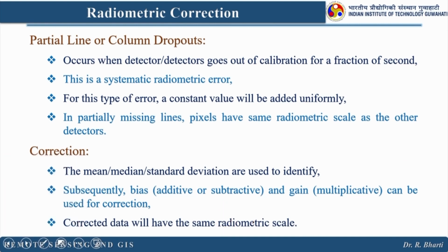So, again during the measurement, however it was having some error, but it has limited itself between 0 to 255 in 8-bit data, but after correction also it should not go beyond your radiometric resolution, that means it should be between 0 to 255, right.